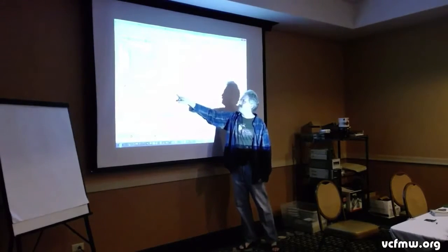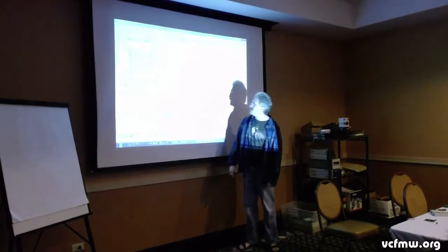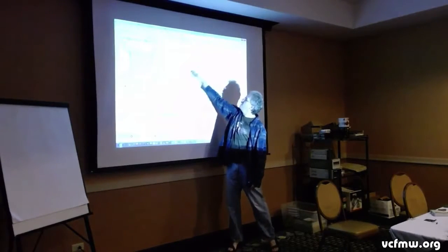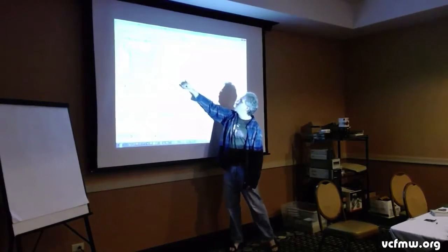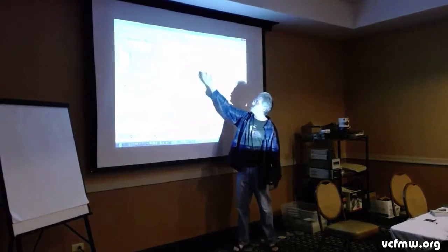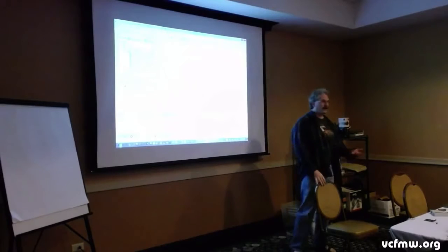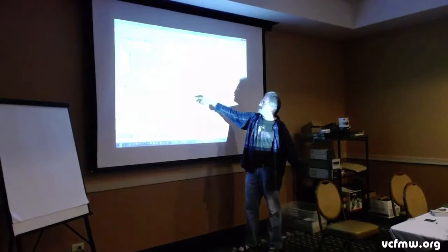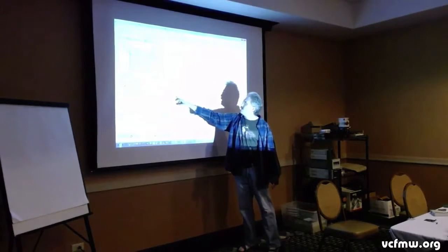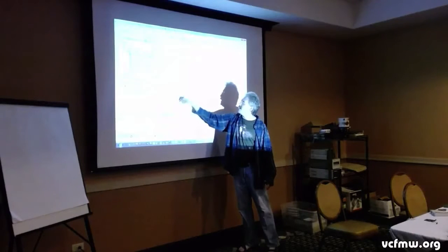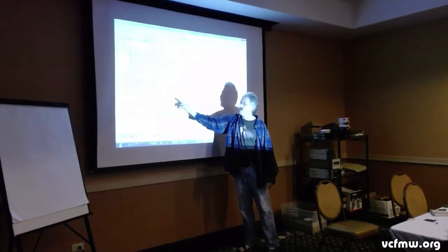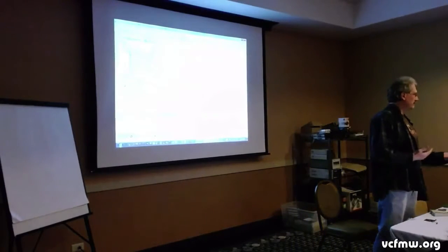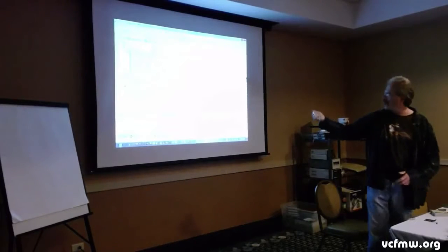If reset, this little thing right here says assign the reset value to the output, which is Q. Q is defined here, and the output is right here, Q, which in this case is width minus 1. Width normally is 8, so it'd be 7 to 0, or an 8-bit register. Q is a value that can be stored to it in the reset state. Normally it's set to 0. But if the enable is turned on and the negative clock happens, then assign the D value to Q, which, for those of you who know a flip-flop or latch, says assign the output to the input and hold it there. So, a little bit of quick code right here.